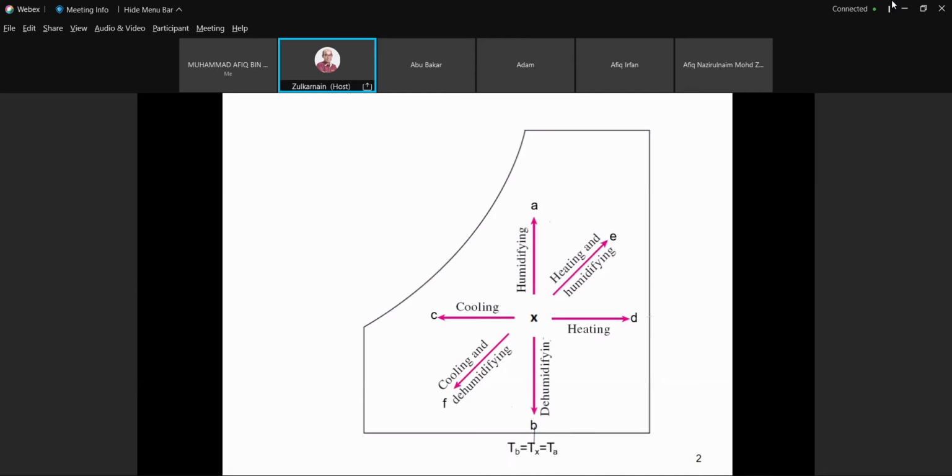Okay, so this is the value of temperature, the dry bulb temperature. This is the value of the change in omega, omega F and omega B. On the top part is omega C and omega E. And then we have TE and TB, the dry bulb temperatures, and also the dry bulb temperatures for the cooling process, TC and TF. So when we project all the lines horizontally, this is what we have. When we project the lines vertically, this is what we have.